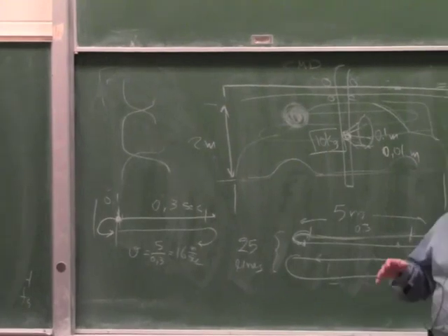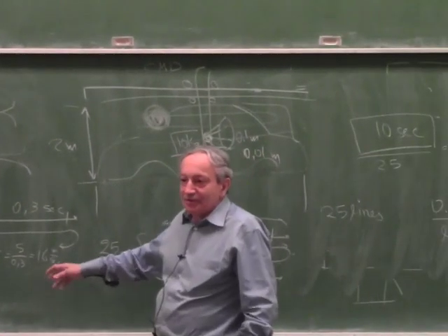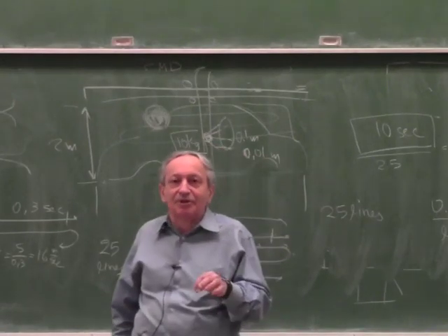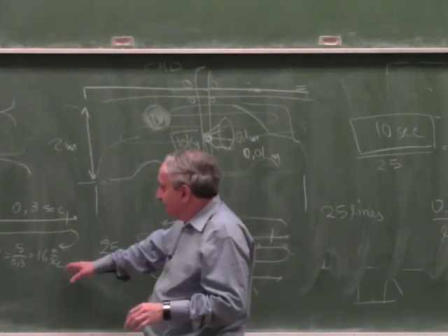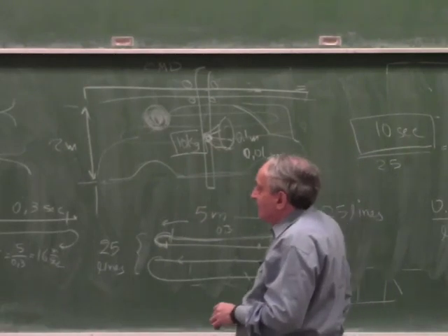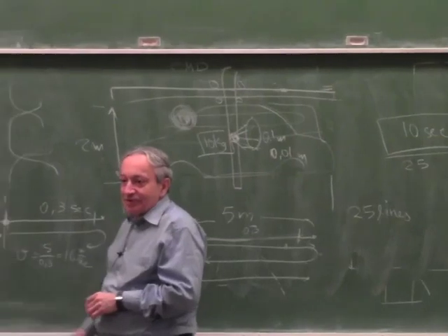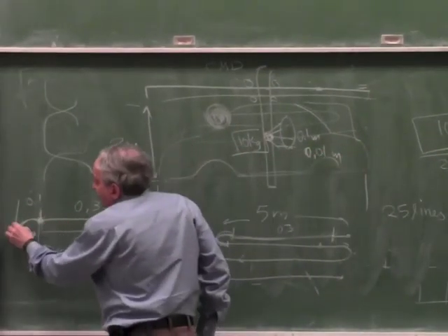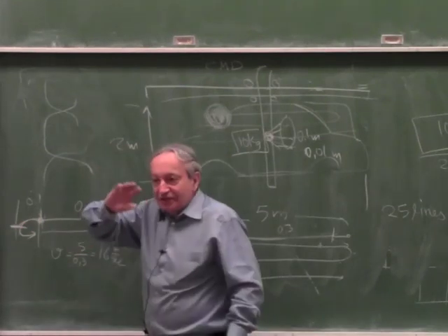By the way, in the exam as well, all calculations can be rounded. You don't need a calculator, because it says on the exam you only need to calculate to plus minus 20%. So don't bother with calculators. You just say roughly 16 meters per second. Now I can calculate the acceleration, because you have the time. It's easiest to calculate on half the time, because 0.1 second is for the whole reversal.